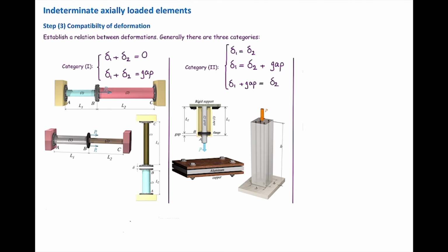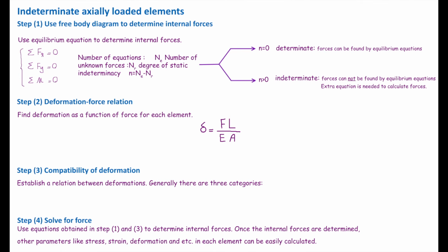The third case is the one that we just talked about, where we need to use similar triangles. And the last part is combining the equations that we got from equilibrium in step 1 and the compatibility of deformations in step 3 together in order to solve it for the internal forces. And that's it. This is the process for analyzing indeterminate axially loaded elements.